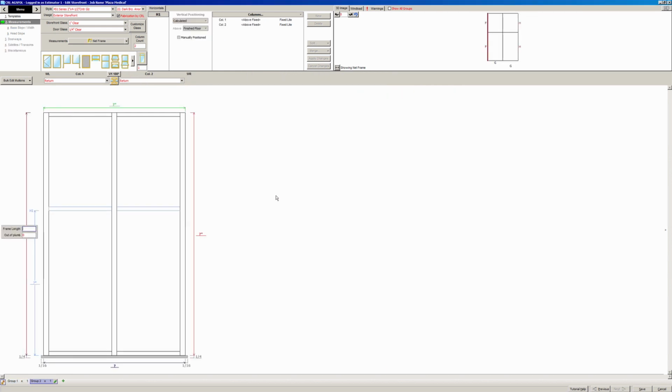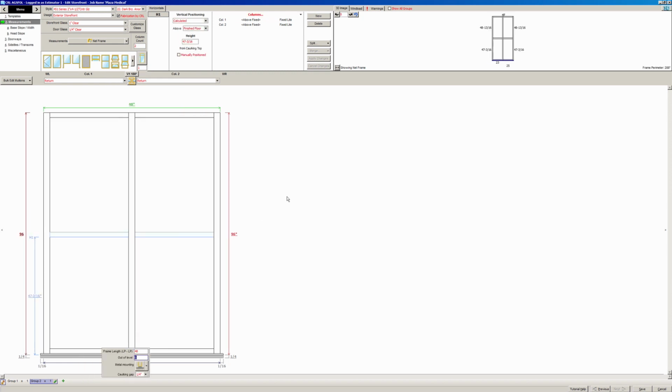Double click that elevation, type in the height, type in the width, and it automatically adds that elevation. To change the quantity, and if you want to label this elevation a different mark, simply click on the pencil to that tab on the bottom left. This first field here will allow you to change the elevation mark and your quantity as well.